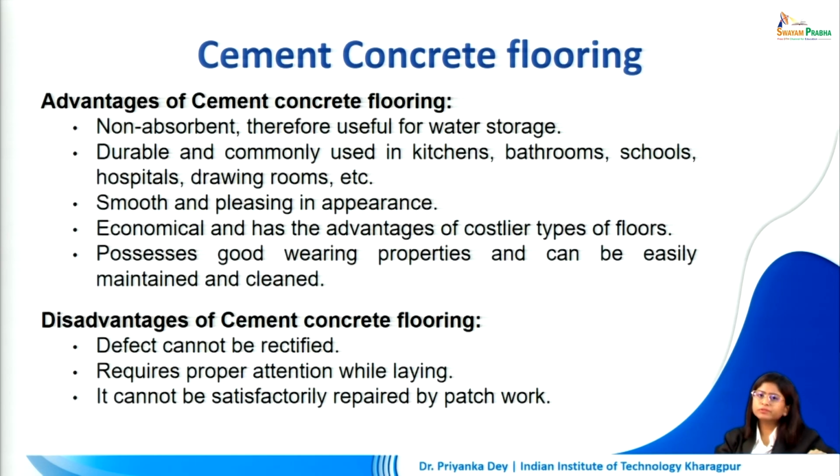The advantages of this type of flooring is that it is non-absorbent, therefore it is useful for water storage, durable and commonly used in kitchens, bathrooms, other public buildings. Smooth and pleasing in appearance, it is economical and has the advantages of costlier types of flooring, and it possesses good wearing properties as well. It can be easily maintained and cleaned over the duration of the lifespan of the building.